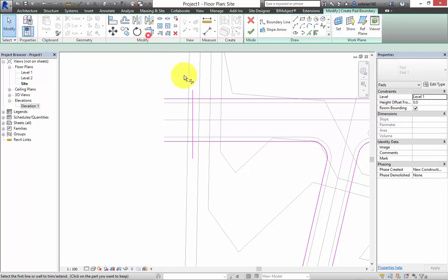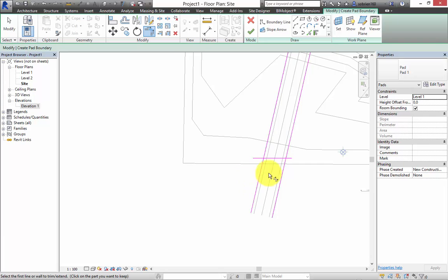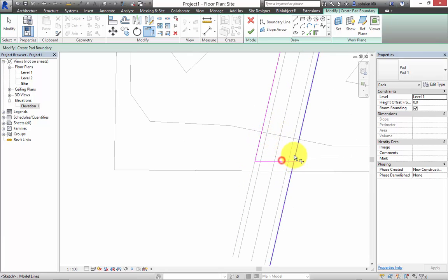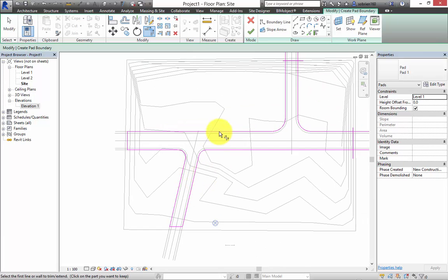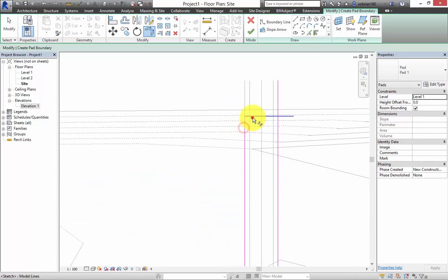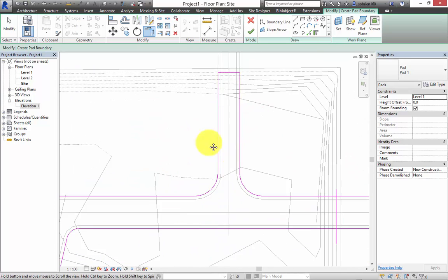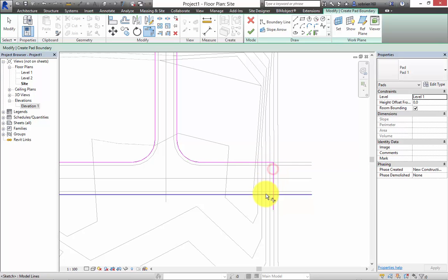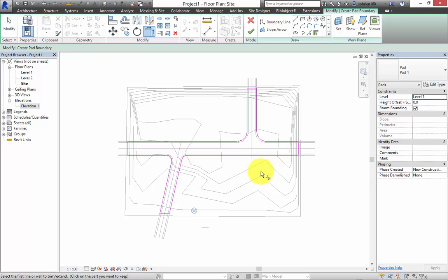And then we use the trim tool just to trim the edges, like you always do when you're dealing with these profiles. Okay, so you'd end up with something like that before you do anything with it. Then I'm just going to make sure that we put it on the right level. Going to put it on road base. And accept it.